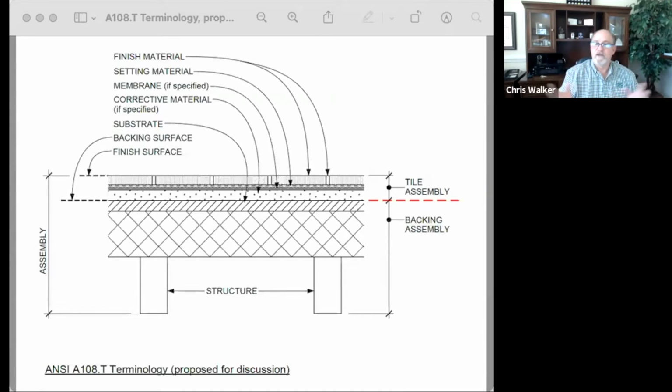So we spent years debating L over 360 and 240 and 720 per stone, and I don't know how many tile guys can go into a place and say, well, this structure is not suitable for a tile assembly because there's too much deflection. I'm not an engineer. I simply want to be able to focus on my tile assembly. So yeah, to Scott Conwell's point, cleaning that up and having a starting place, while that seems maybe overly simplistic, is kind of a big step, because as you mentioned before, it's really been fairly undefined, and people defined it to their pleasure or whatever suited the purpose at the time.